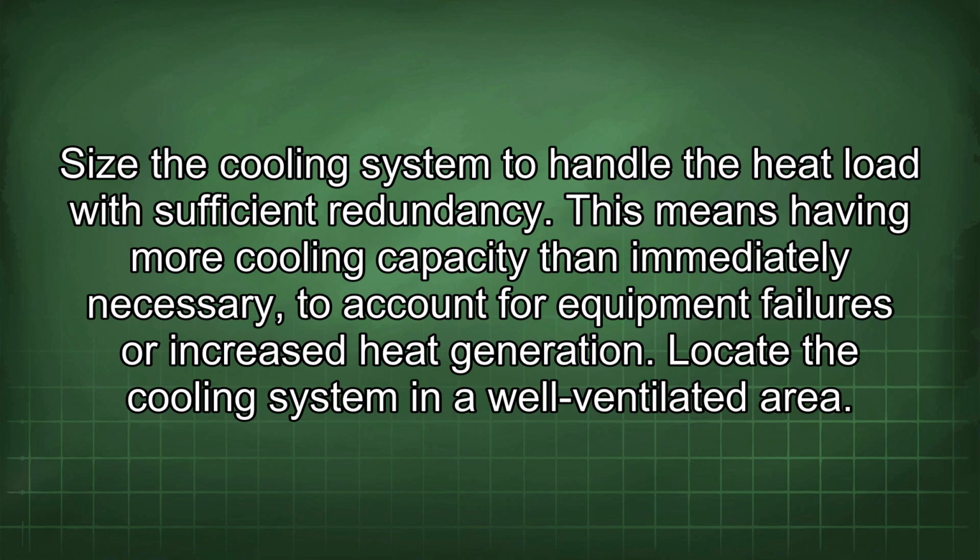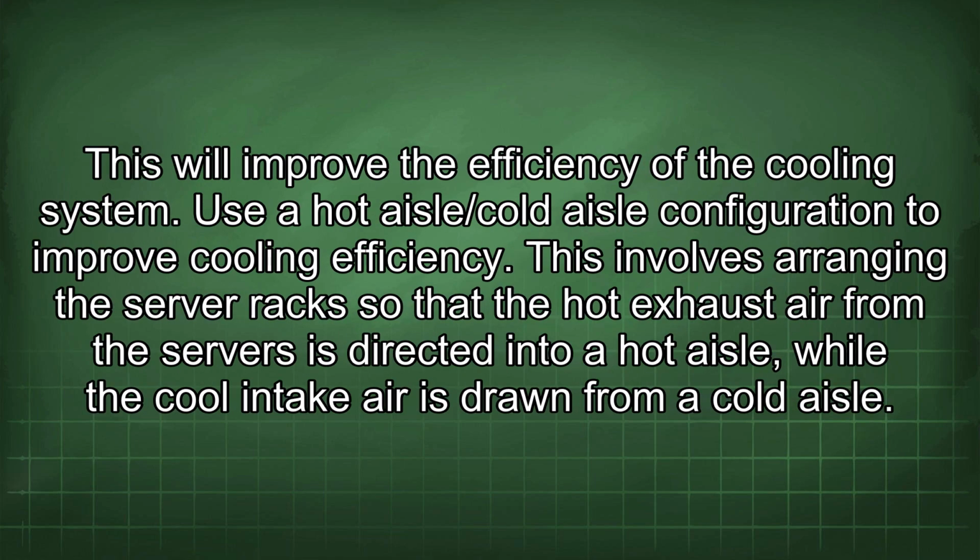Size the cooling system to handle the heat load with sufficient redundancy. This means having more cooling capacity than immediately necessary to account for equipment failures or increased heat generation. Locate the cooling system in a well-ventilated area. This will improve the efficiency of the cooling system.